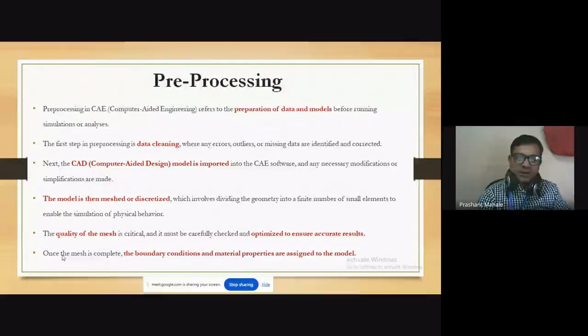In such cases, it also asks for the G value, the modulus of rigidity. There is one more selection that you have to do, which is shell selection, element selection. That element indicates a solid body, a hollow body, or a simple beam or plate.